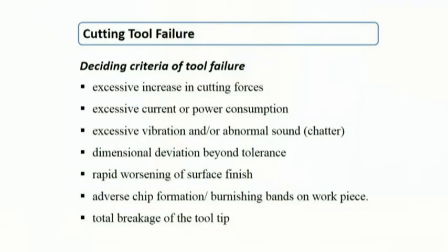So there may be some kind of vibrations at your work holding devices or tool holding devices, and these vibrations may result in chatter marks on your machined surface. So if you observe chatter marks on the surface which you have machined, that also indicates your tool has failed.